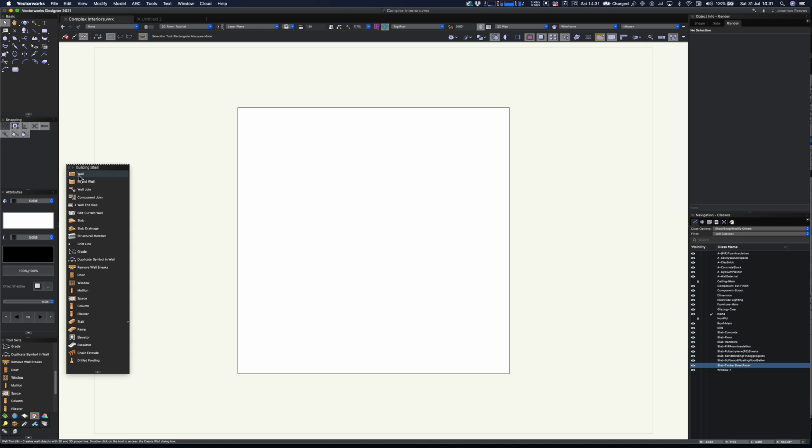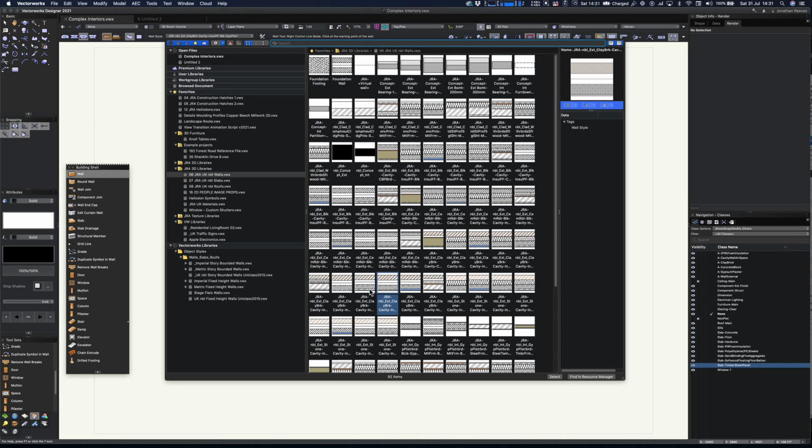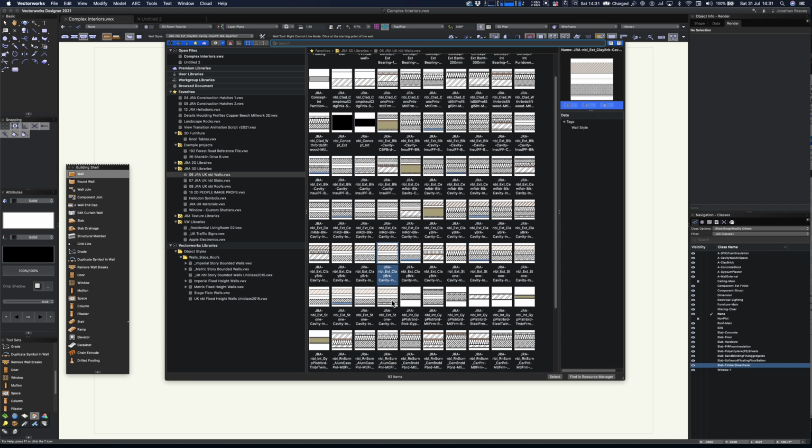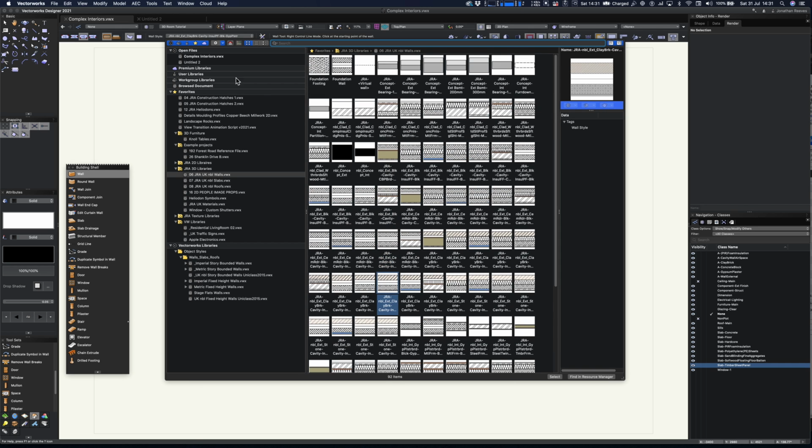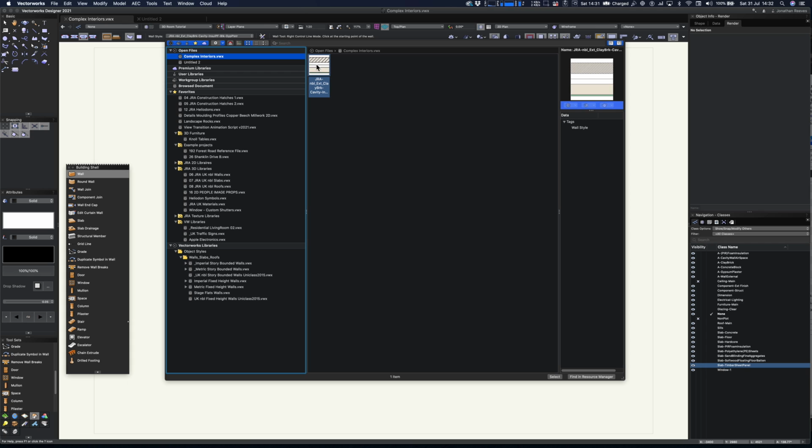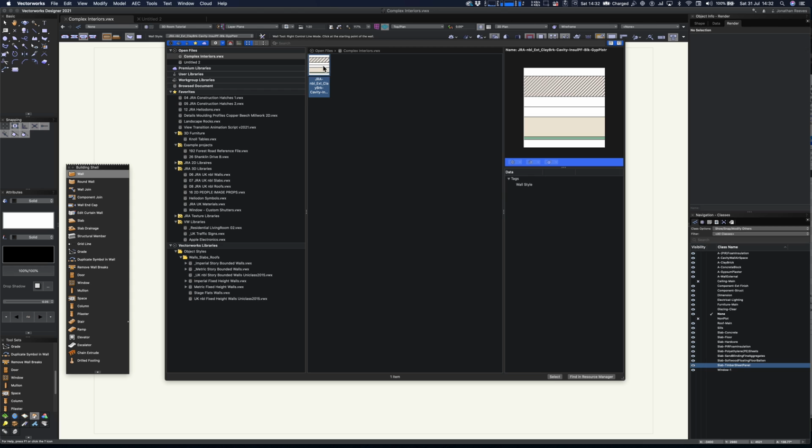The next critical step is the walls. And what we'll do is select the wall tool. We'll go ahead and choose a ready-made wall tool from the libraries. Again, you can see I've got some really great libraries here that I sell on the store as well. So check those out. Okay, I'm going to go for this one, which is the one that I've decided to use for the tutorial. Nice, just simple brick external wall with a bit of plasterboard.